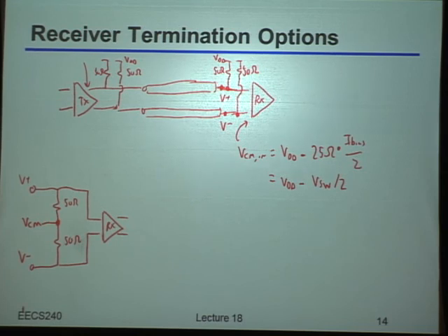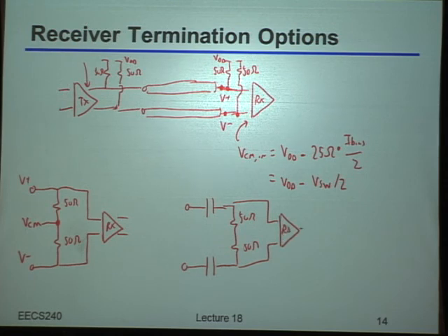Yeah. Okay. So you said actually the next, and let's say final option. You said, well, look, if I really want to set the common modes independently, then what I would do is something like this. I would put AC coupling capacitors in front of everything. Then I would take my 250 ohm resistors, feed that into my receiver, and then indeed, I could put the common mode in the center tap right there. In terms of setting the common mode, this indeed would absolutely work from that standpoint.